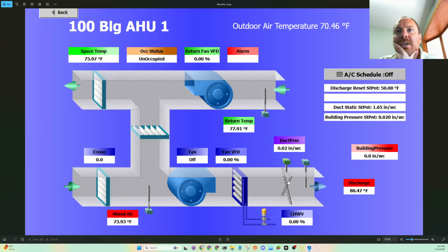Hopefully that makes sense. This sensor is typically a needle in the haystack. It's installed like two thirds of the way down the duct system. Who knows where it is most of the time. And this fan pressurizes the duct system for static pressure.